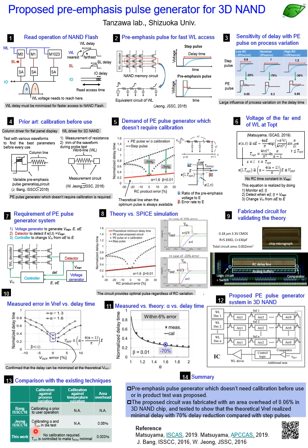On the other hand, using this proposed feedback circuit system, you don't have to do any calibration process or additional test. You can always get the optimum pre-verse pulse even under temperature variation, because this feedback system is effective in every single operation.